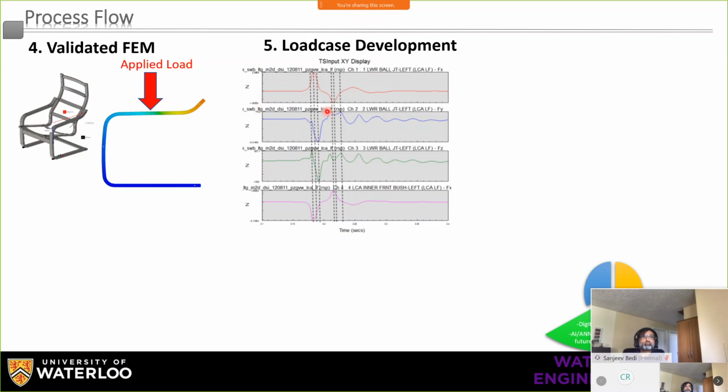But this is a simple case of just measuring forces, let's say, and we can see that there might be a peak and a valley here, and those load cases would be deemed significant. And then there might be some oscillation occurring after we sit on the chair, and those are non-damaging because the actual amplitude is a lot less. Okay, so that's important because when we collect the usage data, we're going to have a ton of time history data to sort through. An important part of what we're trying to teach the students is how can we effectively filter that data to extract the meaningful parts from it that are actually going to drive the design and remove all of the content which is not significant or non-damaging.